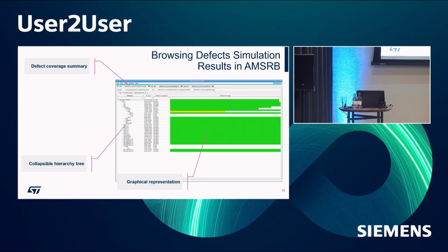Of course, where there is a lack of coverage, this means that either the device was not activated, and you can see that in the slide for the activity coverage, or this kind of fault cannot be discovered by the implemented test, which means, as I will show you later on, that you can enter a loop to optimize either the test or the circuit itself.